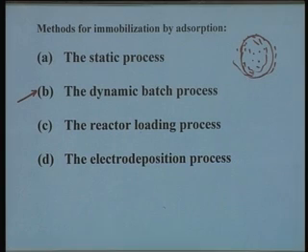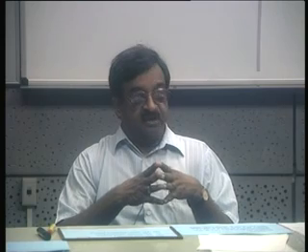Usually in commercial establishments, when we use adsorption as a method of immobilization, we use the reactor loading process. That means, first of all, the reactor which is to be used for bioconversion or the enzymatic reaction is packed with the carrier itself, and then the enzyme solution is recirculated constantly through the carrier bed, and over a period of time the enzyme gets adsorbed onto the matrix.